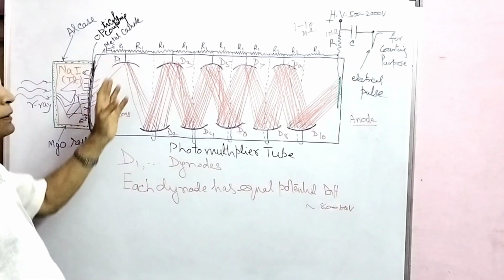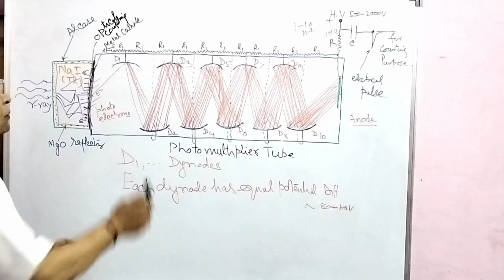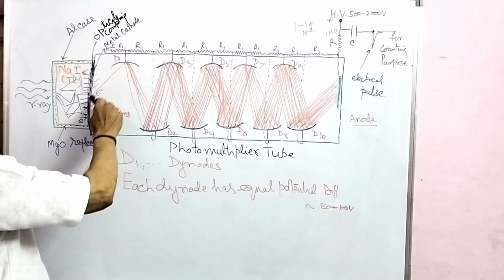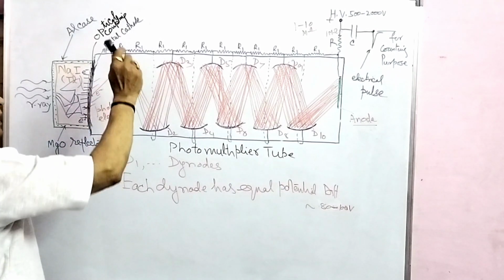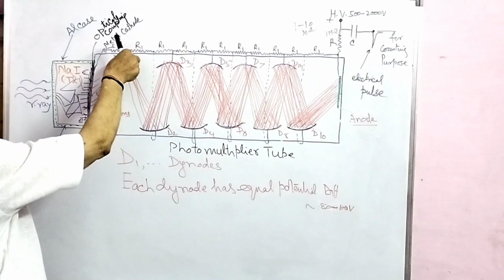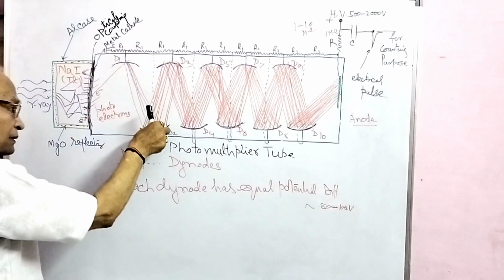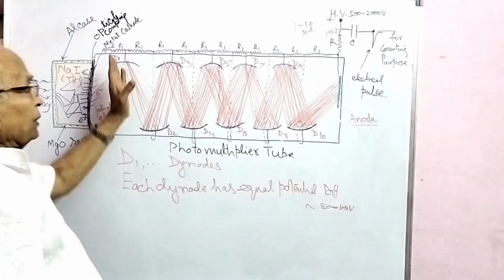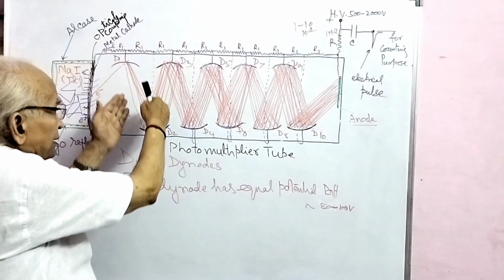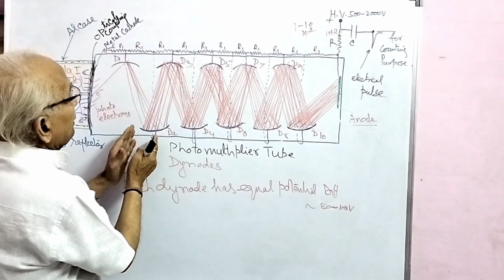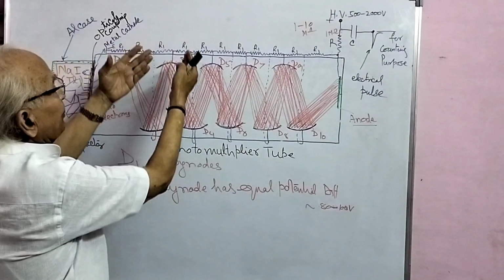So the multiplication takes 5 times, suppose. So this one electron and second or third, all electrons giving 5, 5, and then these are focused to the second anode which has the same potential difference. So further acceleration, multiplication, this is attracted toward this, so more multiplication.